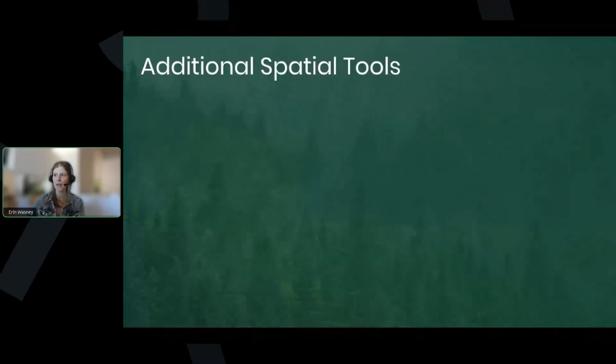Okay, so that was kind of group of tools number one. We talked a little bit about how to import, and then we covered a few different tools for allowing you to control that survey data. I do want to re-emphasize, Matt used an example there that from the get-go was well within the quantity of points that we would recommend using. So, keeping your project, I think our recommendation is like 15 million, somewhere around that. So above that number, that's where those tools really come into play. Yes.